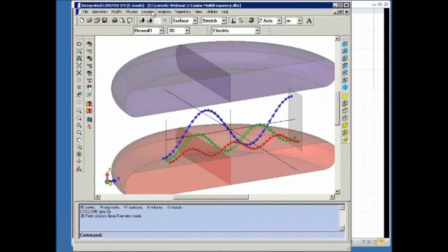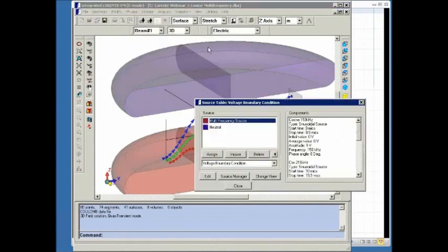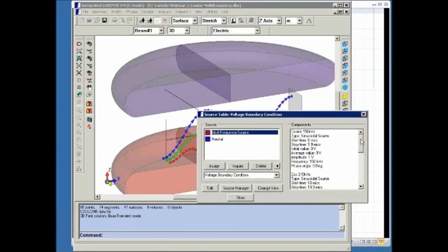So here, if you look at the boundary conditions, I have what I call a multi-frequency source, which consists of 150 kilohertz, 210 kilohertz, and 300 kilohertz. But if you look closely, they don't all occur at the same time. One starts at 0 seconds and ends at 9.9. The other starts at 10 and ends at 19.9 microseconds. And the last source starts at 20 and ends at 30.